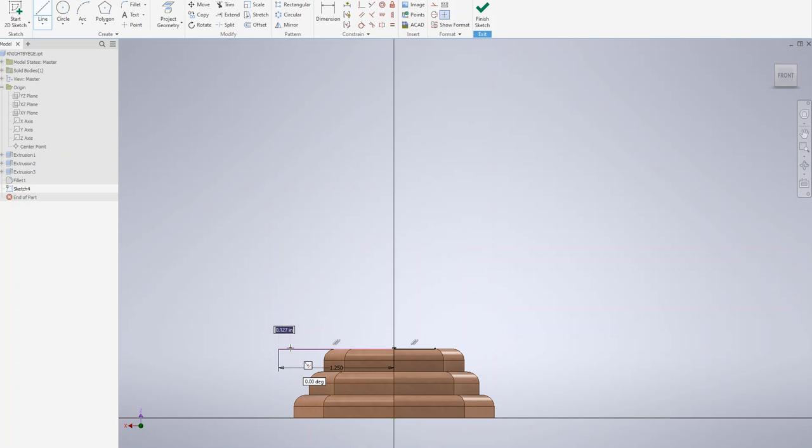Just to see if it's going to work. It did. Perfect. All right, so this is your starting point of the rectangle. You always plan ahead, because this particular line, even though I'm not going to use it later, is called a construction line. And to draw a construction line, actually, the rectangle is also my construction line. Both of the lines are not going to be used, but this is your proper starting point. So that's why I drew this line, which is half of 2.5, which is 1.25.